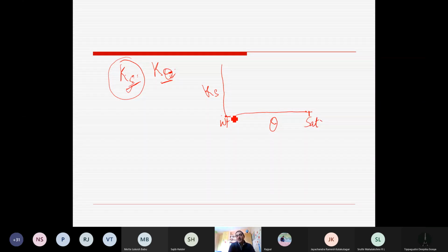Once soil is very dry, it is wilting point condition, or if we have measured the pressure or soil moisture suction in soil, it is minus 15 atmospheric pressure here, and at saturation it is 0. Somewhere it is field capacity, and whatever moisture content theta you want.